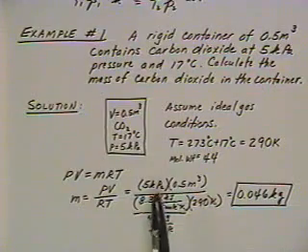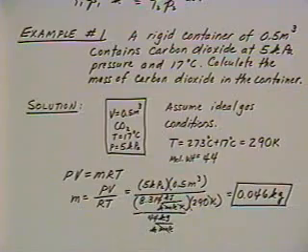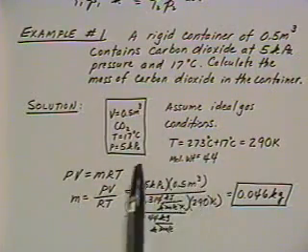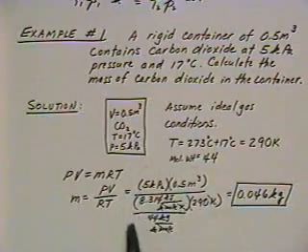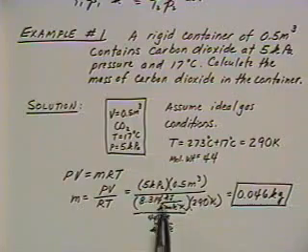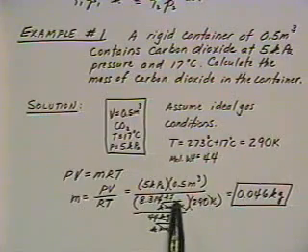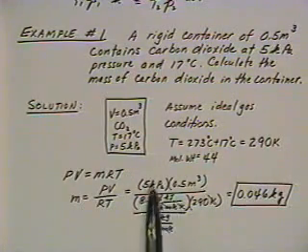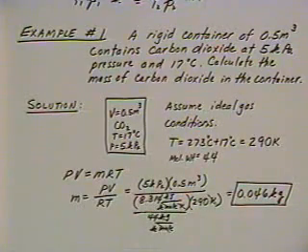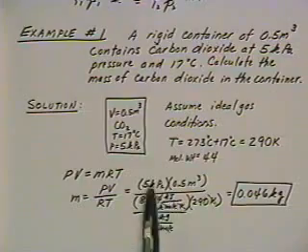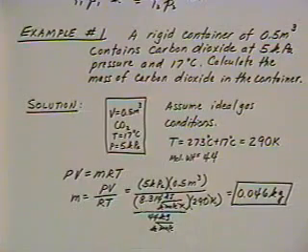Sometimes I've included the units in the problems. If it's a repetitive set of units, I haven't included them, but again, a recommendation is to go through the units and make sure they're compatible. For instance, you've got kilopascals up here and kilojoules here, and so when they're both in the same set of units, then you don't have to worry about that factor of 1,000 that sometimes enters into it if one is in pascals and the other is in kilojoules. So make sure your units are always compatible here when you go through.